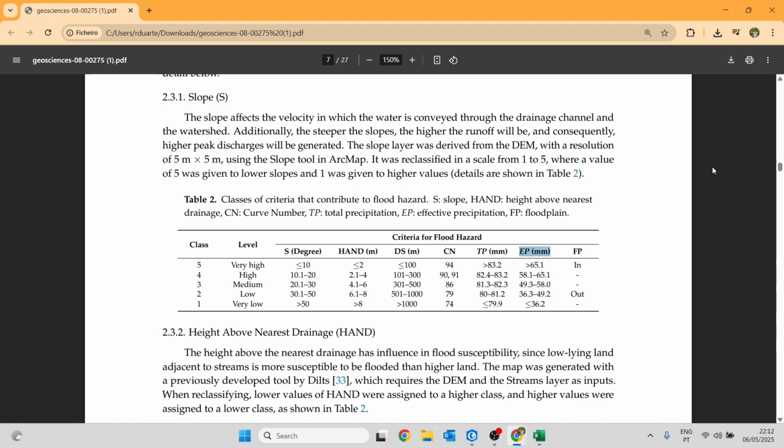It said also that during drier periods, less than 5 millimeters of daily rainfall will not be considered effective, as this amount of precipitation would likely evaporate from the surface before soaking into the ground. Effective precipitation enters the soil and becomes available to the plant. Effective precipitation is calculated based on an equation that requires both the total precipitation and the curve number values.